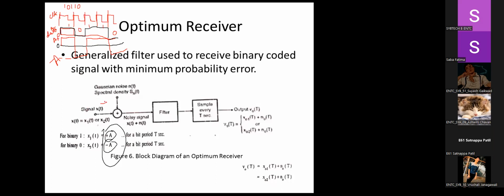So what kind of input signal are we giving here? It is the input signal to the receiver. When we were coding, before entering into the channel, the line code technique we used is polar NRZ, that is non return to 0. And when I say the logic of 1 and 0, then we are talking about the binary phase shift keying signals, BPSK signals. All right, I think you have already dealt with that.